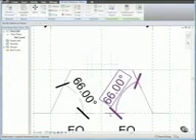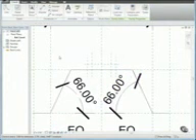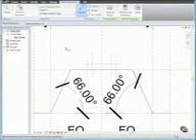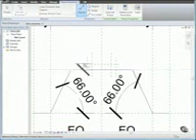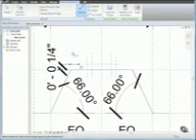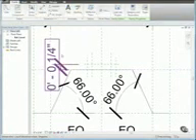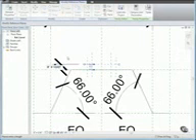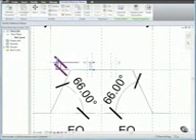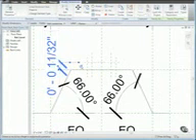and click OK. Next, let's dimension and constrain the dovetail. From the Dimension panel, click Aligned and dimension the reference planes at the top of the profile and the dovetail horizontal reference plane. Then click Modify, select the horizontal reference plane, then click the dimension and type 11/32 of an inch. Then select the dimension and click the lock icon to lock the distance to the horizontal reference plane.